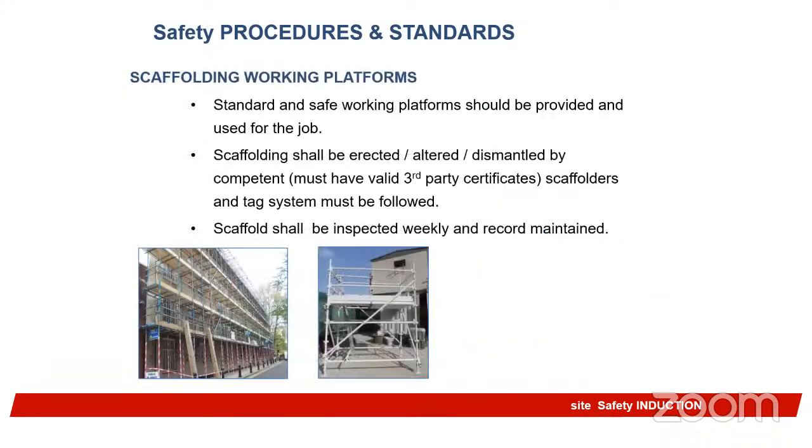Your scaffolding working system or working platform needs to be talked about. Scaffold induction, you just need to go briefly because there are so many things to talk about when it comes to scaffolding, when it comes to induction of workers for scaffold. Standard and safe working platforms should be provided and used for the job. Scaffolding shall be erected, altered, and dismantled by a competent person, and must have valid third-party certificates. The scaffold tagging system must be followed. Before a worker uses any scaffold, it must be properly tagged for use.